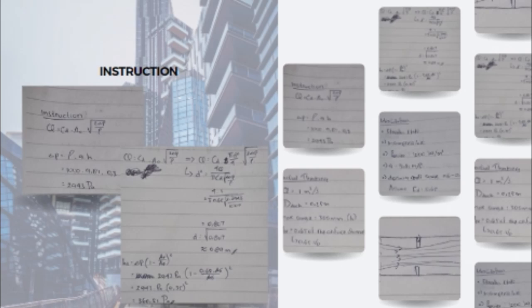After we find the D, we can find the head loss using the equation head loss equal to delta P times open bracket 1 minus Av per A0, where Av is the area of the vena contracta and A0 is the area of the orifice meter, close bracket squared. So we input the numbers, and we get the head loss is 360.51 Pascal.